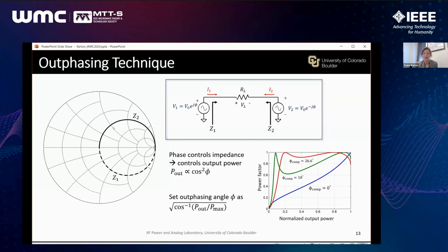On the Smith chart, the load trajectories look like the ones in black, which actually are not great for most power amplifiers. And so what Henri Chireix developed when he came up with this idea in the 1930s was to introduce compensating impedances to shift the upper trajectory down and the lower trajectory up, so that we get a load modulation of both PAs that to some extent hugs the real axis of the Smith chart.